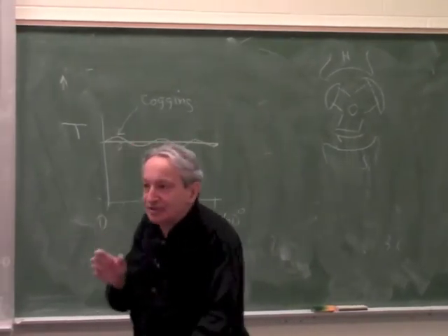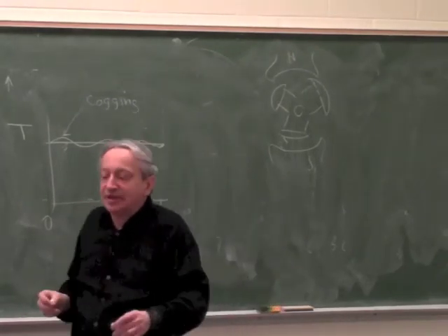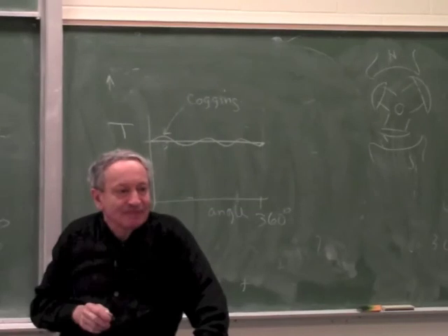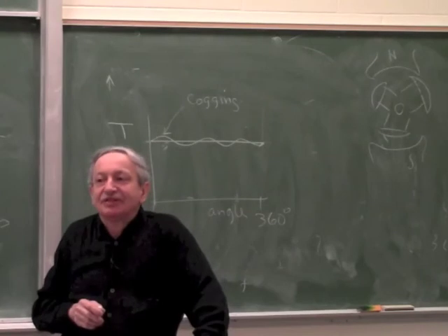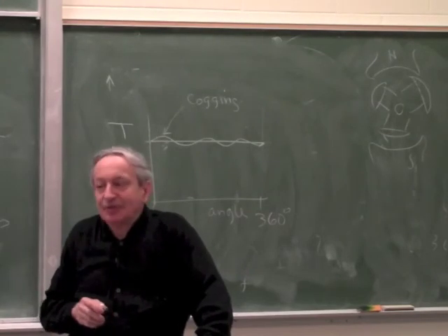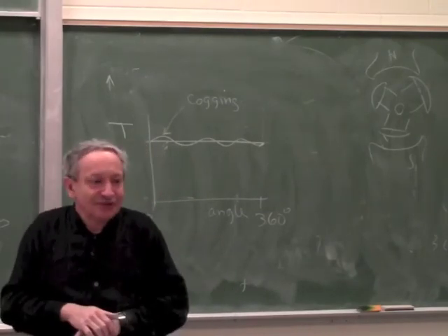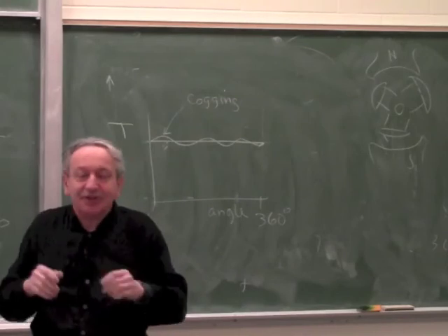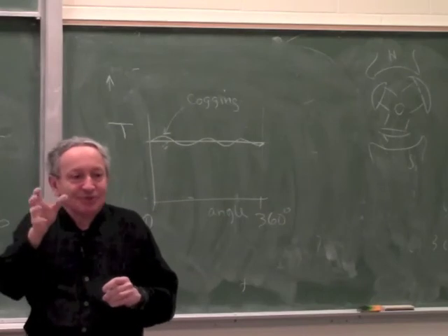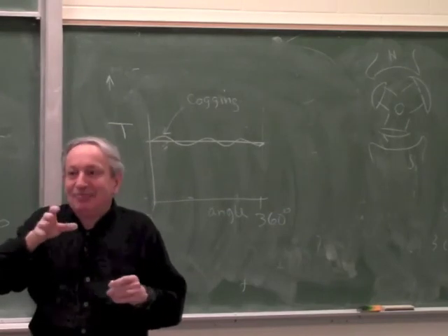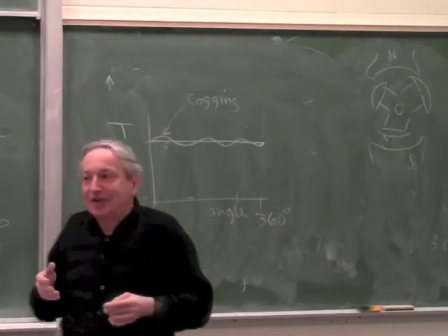Because the servo system is going to position it. If the motor has an encoder, the servo will position it correctly, so why do we care? Non-linearity in the control? Correct. Actually, it's not even non-linearity, it's fluctuating gain. Because we give it a current, we want to have a torque. If we look at the block diagram of the whole servo, there is a block, the actuator. Input is current, output is torque. But if the output depends on the position, it behaves as a nonlinearity, although it's still a linear system, but position dependent.